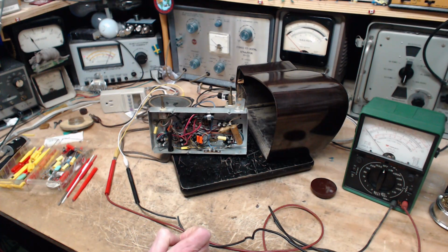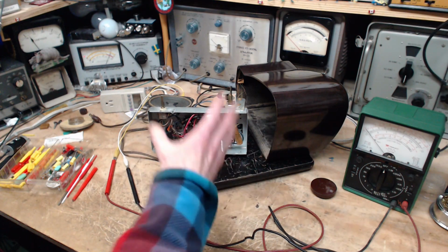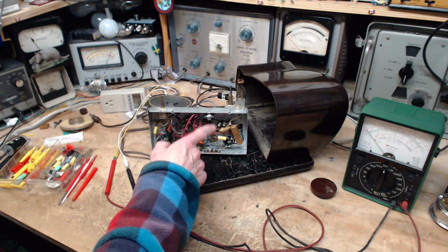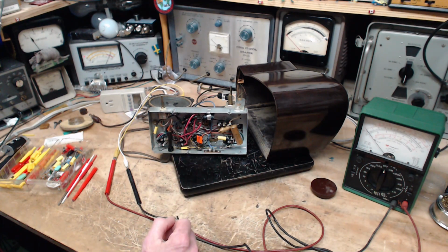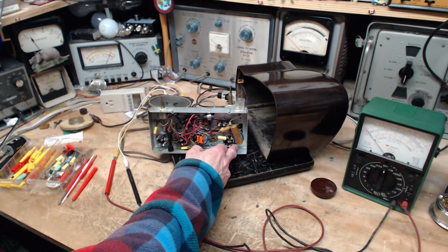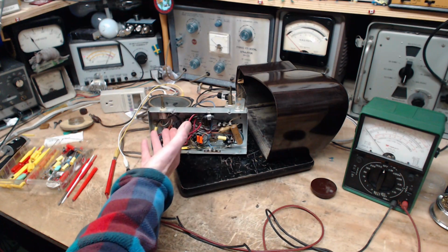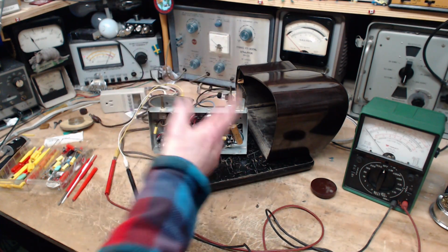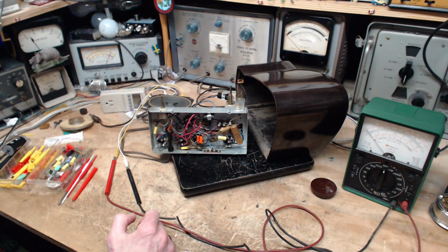So a couple of approaches here. There's a couple of big approaches. One is, cut it out, put another capacitor, and see what happens. No, I'm not doing that. Another one is to test this in the circuit somehow. How could that be done? And another one, the one I'm probably going to do, is to cut one leg off, one wire, one lead. The capacitor is no longer involved in the circuit of the radio. It's free at that point, even with the other lead still connected. And then I can perform tests directly on the capacitor, including, well, I can do quite a number of things.